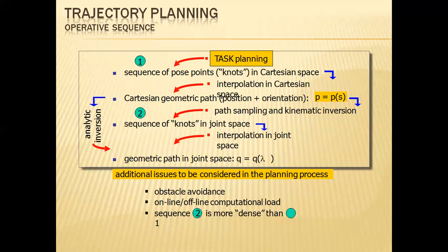And beyond that, additionally some issues have to be considered, such as obstacle avoidance. Just as we discussed previously, if the track has been specified perfectly, there is no issue. If the track has been disconnected, that needs stopping conditions. So for that, the sensors play a major important role. They will give the signal feedback to the controller, and the controller will stop the execution of the program right at that particular point. So it stops the entire process commencement in the form of actions.